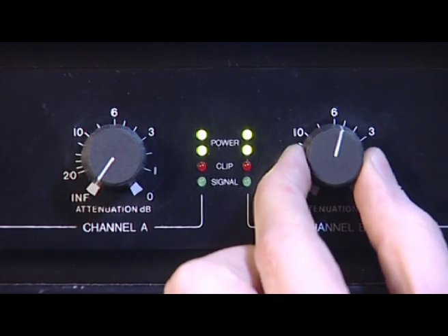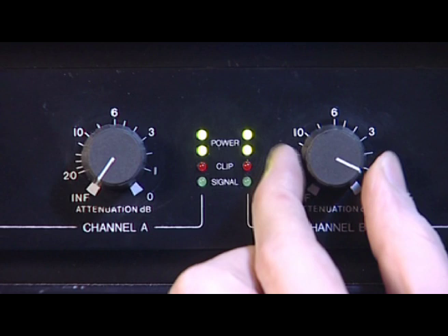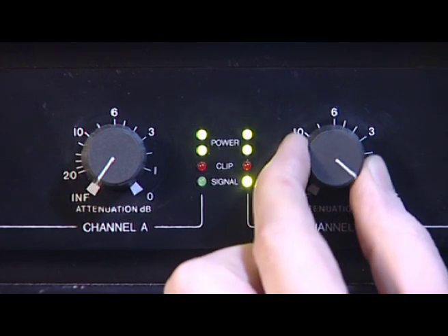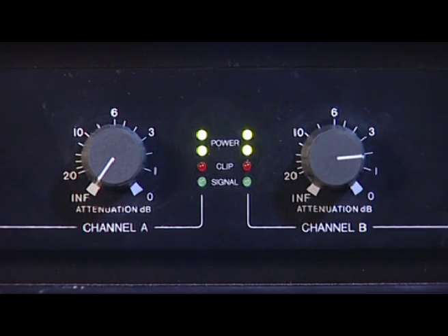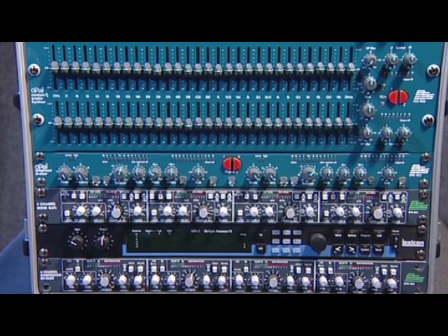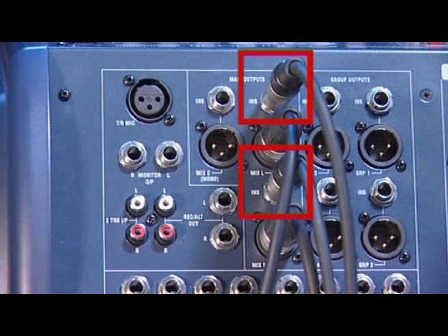Ringing out the system before the sound check is a good way to reduce the danger of feedback. You need to remember that during the process of ringing out, you can cause severe feedback which can damage loudspeakers, so be very cautious when turning up levels. Here's how it's done. Put a graphic equalizer into the mixer's mix insert points.